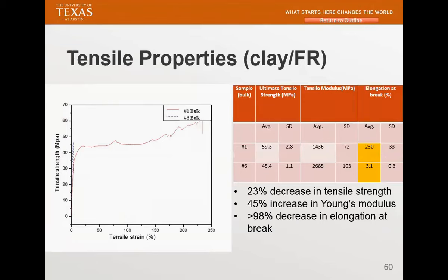Okay, so we did all this. Well, the killer is elongation at break. You read the literature, everybody puts the intumescent in there. You get what you want, but the elongation at break, take a look at that. The neat one is 230%. We have a UL94 V0, but elongation is really bad. It's only 3%.